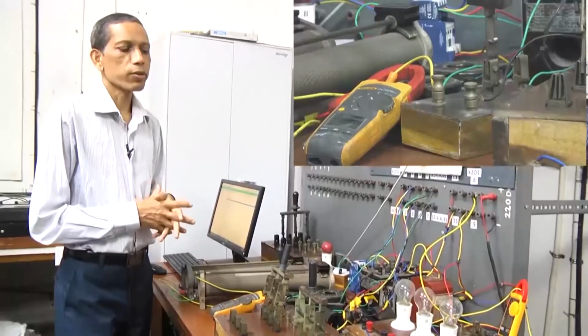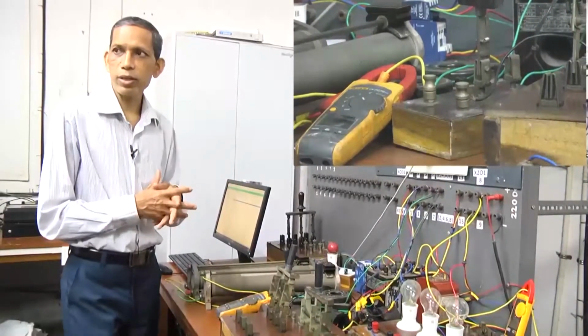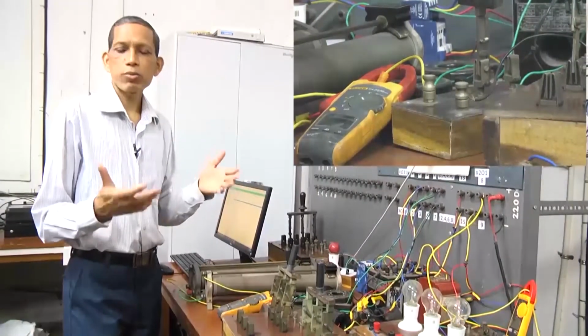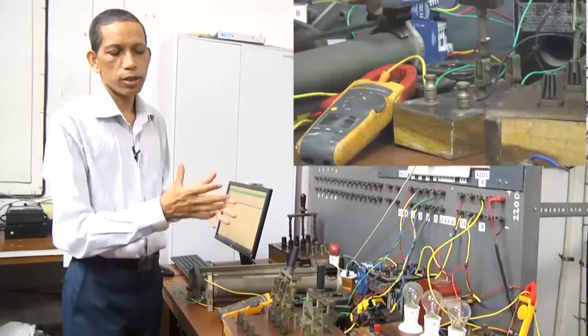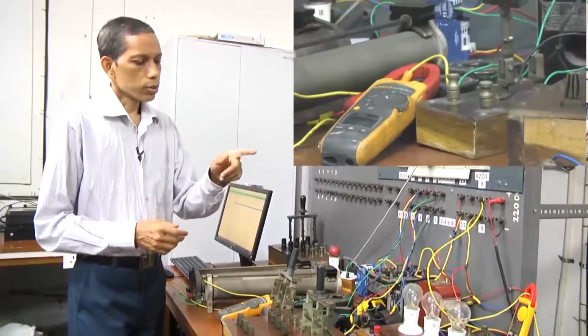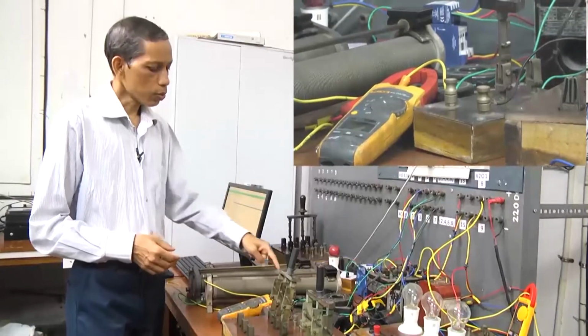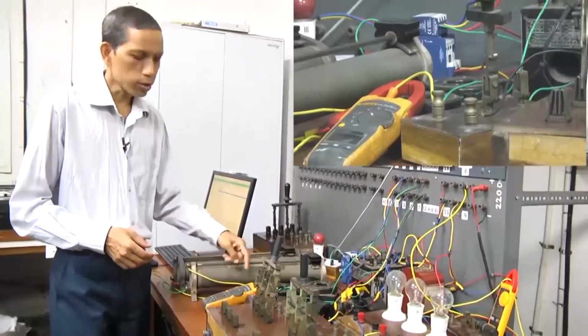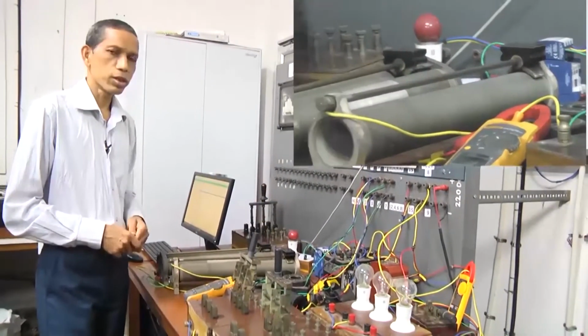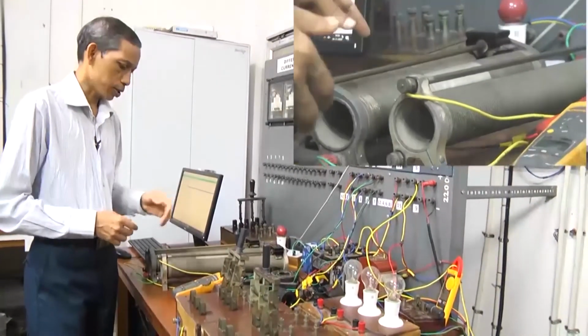Why have I considered star grounded? It is easy to understand for us, for clarity. Otherwise, someone can take any connections based on the requirement. So, both sides are star grounded. We have 2 CTs on the neutral side also, which are connected to the relay for the particular applications.